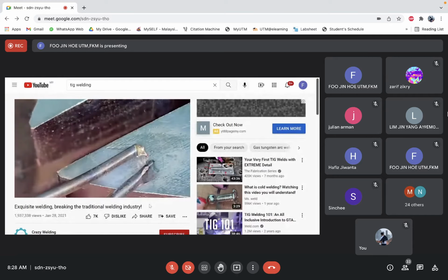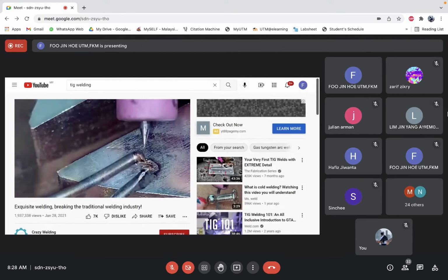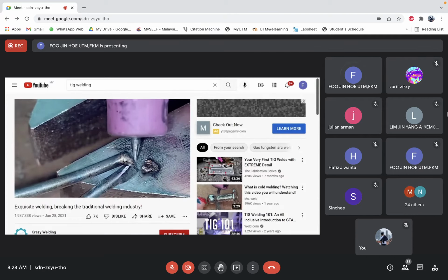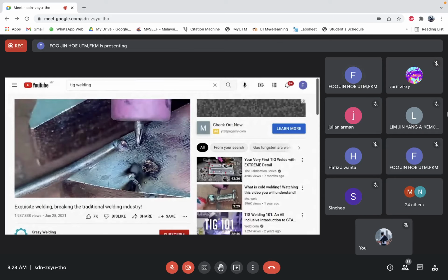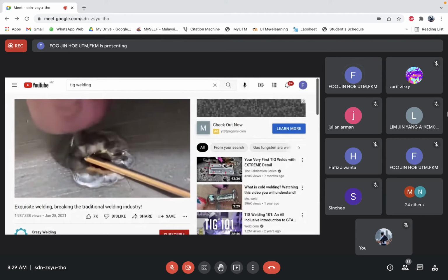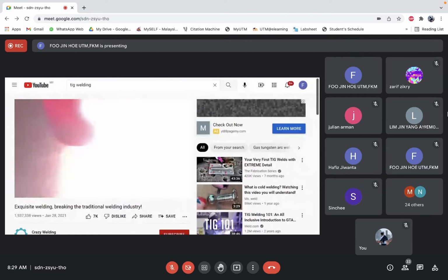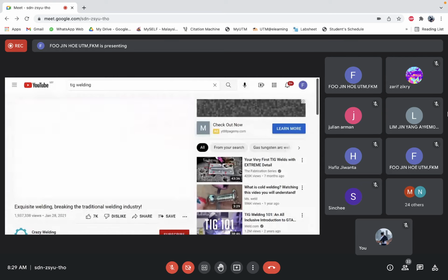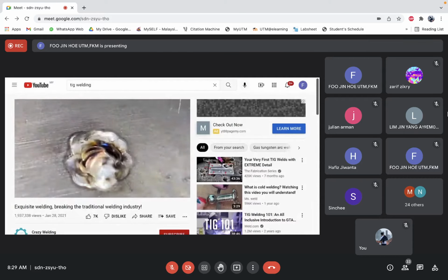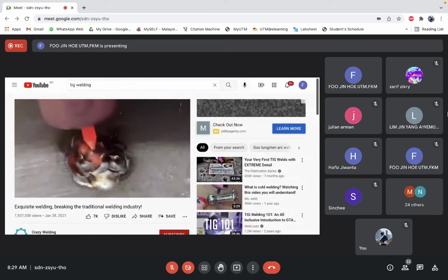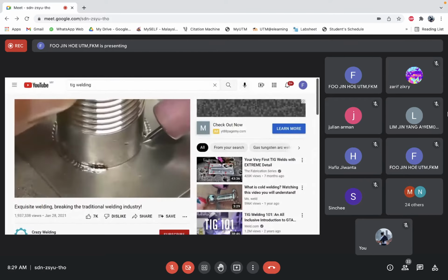The welding parts, the welding construction conditions, plate thickness, groove shape, welding position, welding conditions, post-weld heat treatment, and welding operations, etc., and cost. Choose welding according to the steel type of the structure to be welded. For carbon steel and low alloy high strength steel, it is mainly based on the principle of equal strength matching to select welding wires that meet the requirements of mechanical properties.